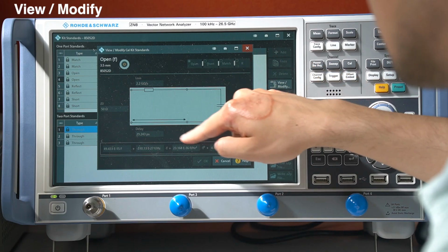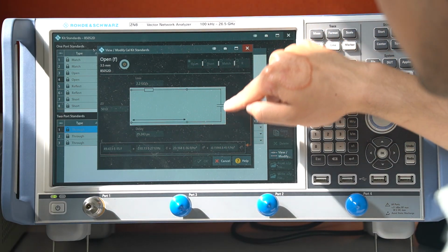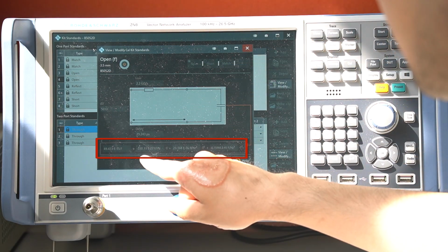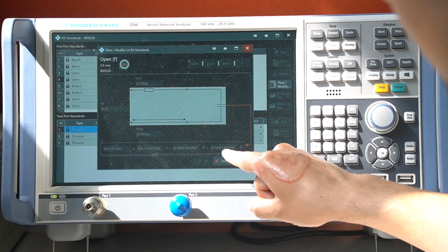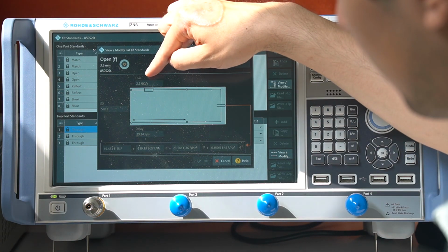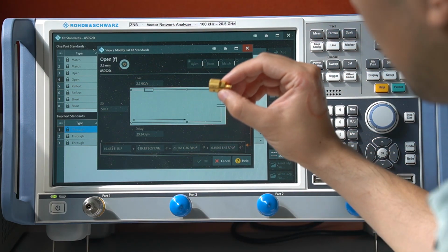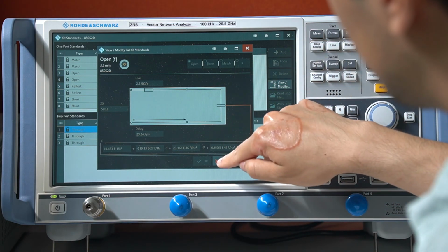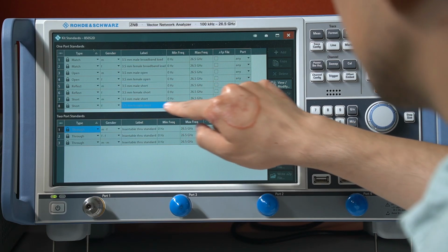So in addition to our open circuit, we also have defined a parasitic stray capacitance that changes with frequency linearly, quadratically, and by the factor of 3. Furthermore, we have a loss factor defined here and the delay factor that depends on the length of the open. And we can check this for each connector, so also for the short connector.